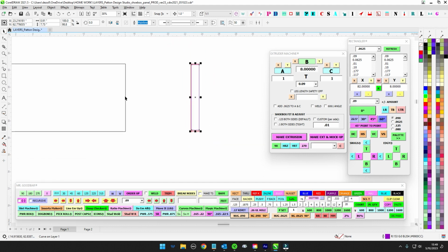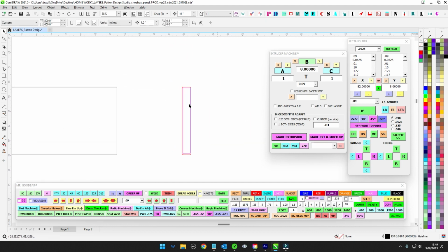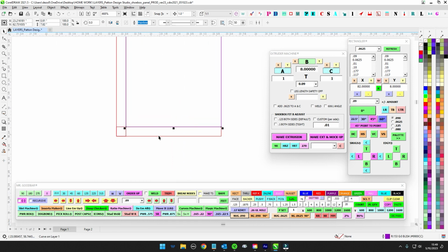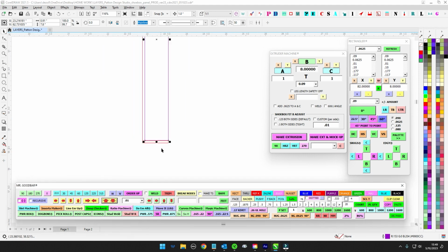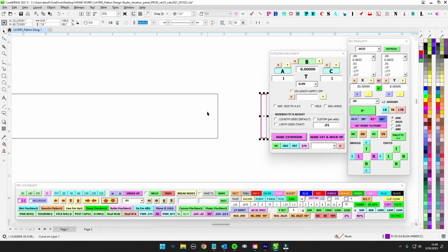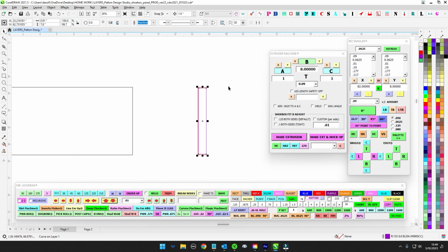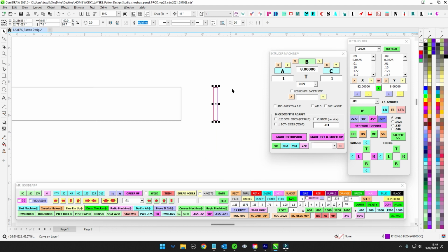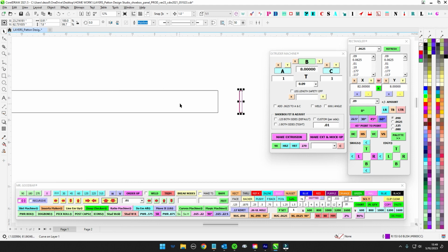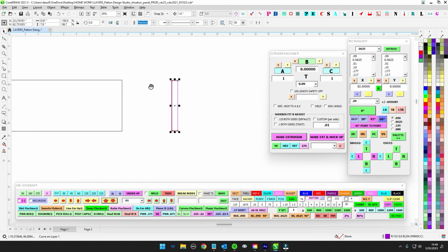But again, if you don't want hardware on the top and bottom and you want this to be friction fit, then you go ahead and leave it at full. And then you're just going to take 0.01 off the bottom of each side. And that's going to be a pretty tight friction fit that the guys will almost have to bump it on there with their fist, and it should stay. You don't want to do a friction fit if it's outdoors or if it's going to see any kind of heavy weather. I wouldn't trust it. You're going to have to put some hardware top and bottom in order to make it stay. But again, it's up to you.